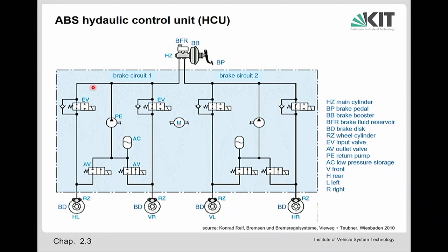No, it's a mechanical valve, but it is controlled electronically. So there is a magnet inside, and if there is a current, then this magnet will shift the mechanical valve, so it will open or it will close. And in this case, it is always open if there is no current, because of this spring. The spring makes sure that it's always in the open position. But the current will overrule the spring, so it will shift the valve to the left, so then it's closed. Yeah? But if the current stops, then the spring will automatically open the valve again. So if a failure takes place, the valve makes sure that this valve is open.